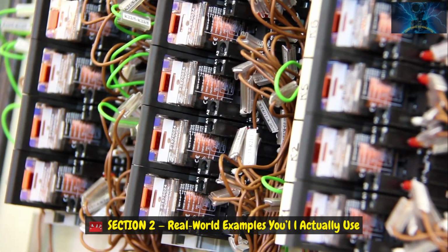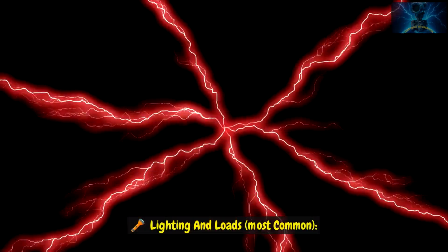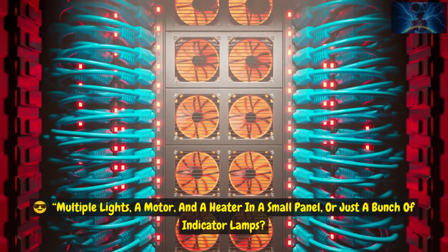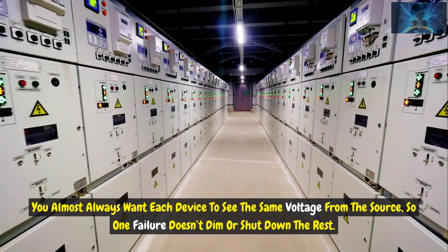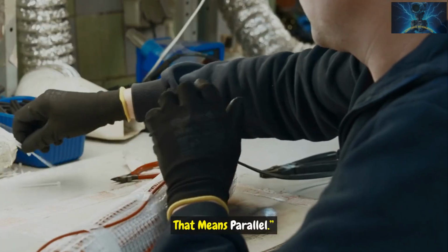Section 2. Real-world examples you'll actually use. Lighting and loads, most common. Multiple lights, a motor, and a heater in a small panel, or just a bunch of indicator lamps. You almost always want each device to see the same voltage from the source, so one failure doesn't dim or shut down the rest. That means parallel.